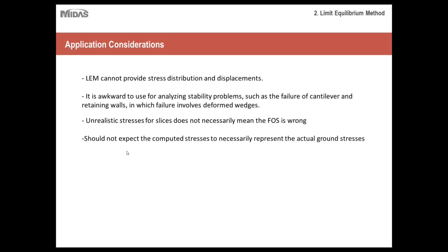Okay, so you should not expect the computed stresses to necessarily represent the actual ground stresses. Just to reiterate, actual ground stresses and computed stresses for your slices are two completely different things. So don't be discouraged, or don't worry if you seem to get stresses that seem to be kind of high or low. As long as your factor of safety is within reason, you should be all right.